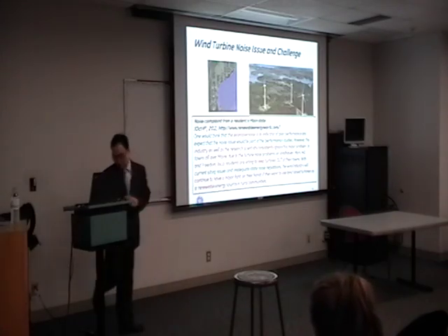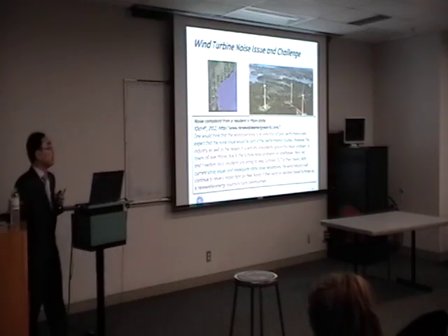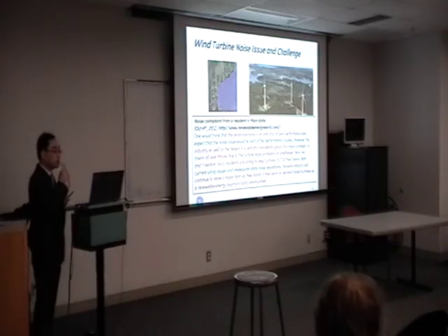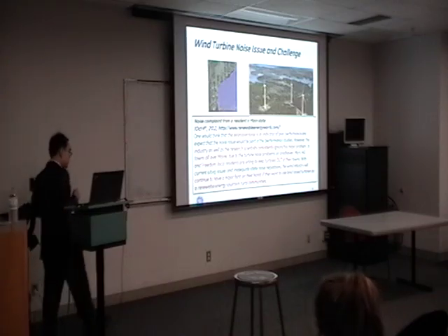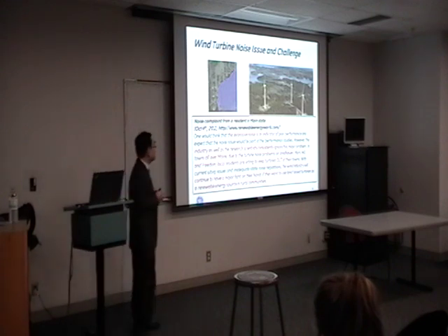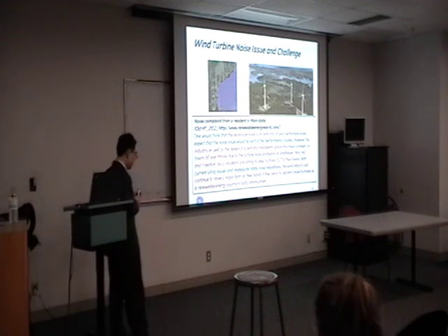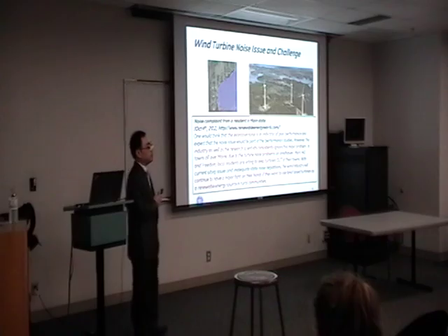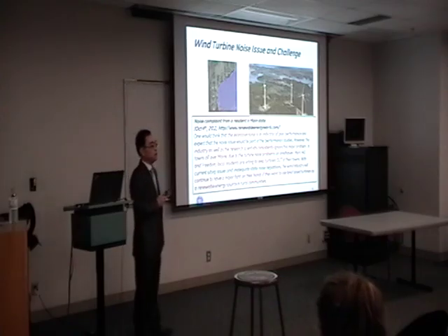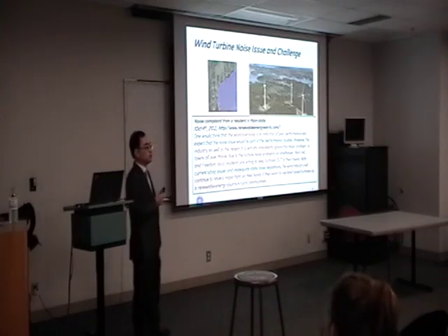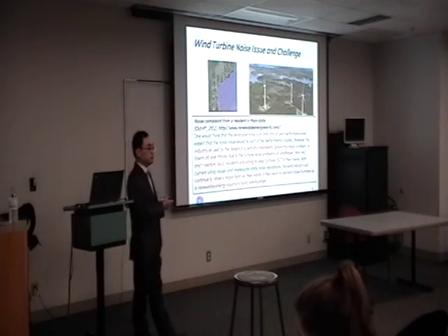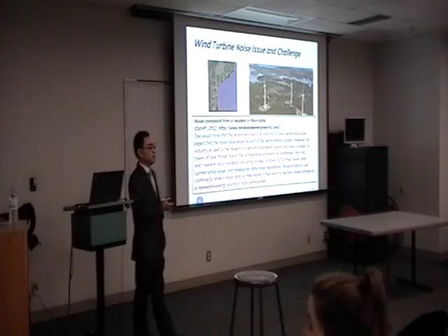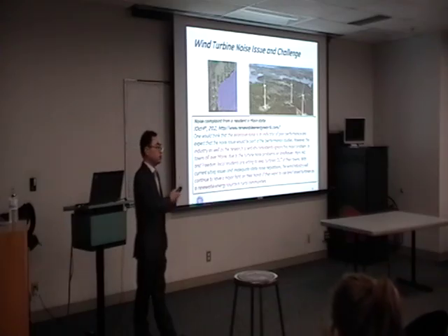Okay, this is my second topic. Your tool, you use only inviscid? Yeah. Viscous effect is not important? It's not included here. Viscous impact is somewhat indirectly included in the polar data. The polar data, the CL as a function of angle of attack, comes from CFD or experimental data. So that includes some viscous effect indirectly.